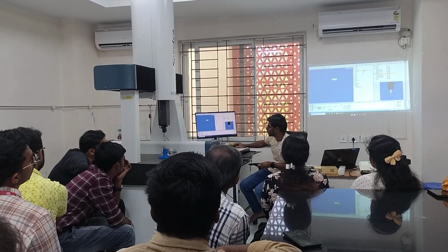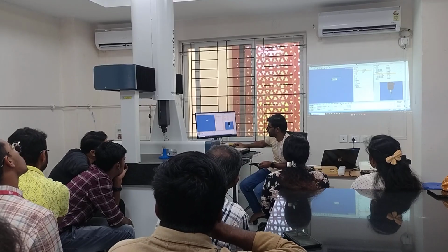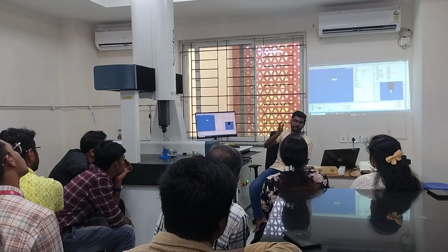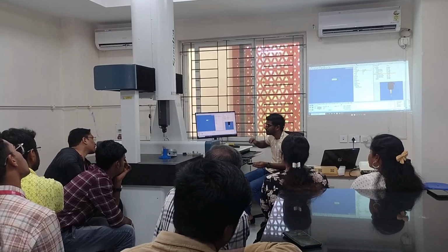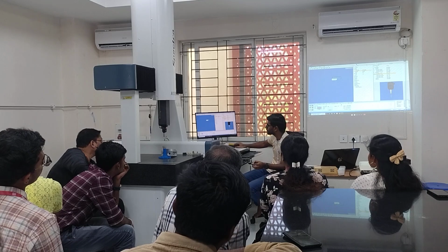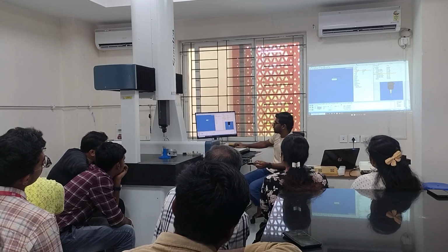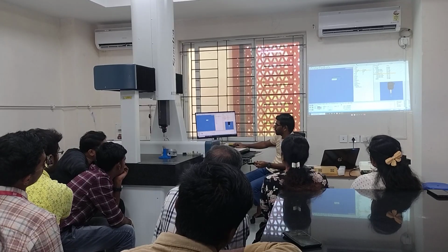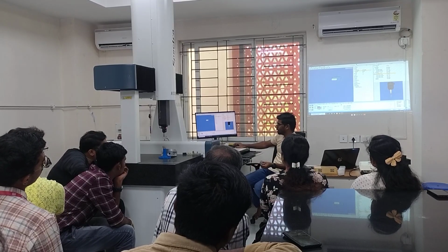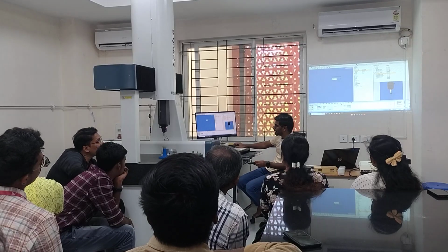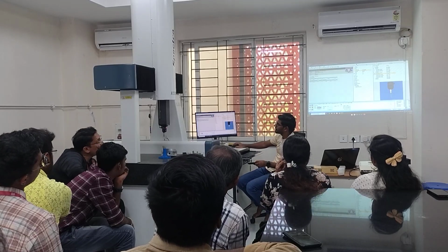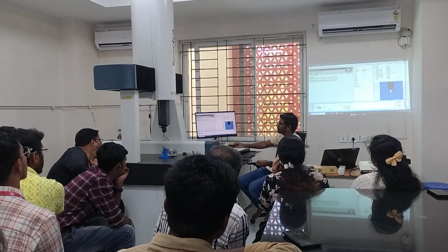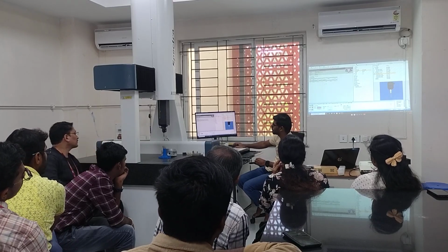But how much are we getting? It is 50.417437 degrees. Okay, so there is some deviation. So that shows that additive manufacturing is not perfect. Even though that is SLA, yes, SLA part. In the drawing, it might sometimes say that the tolerance limit is different. So you can change the acceptable or non-acceptable limits. Okay, I click on accept, again you'll be able to see it here. The inclination angle, it is supposed to be 50, it is actually this much is the deviation. I'm able to see here. So that's the kind of report.